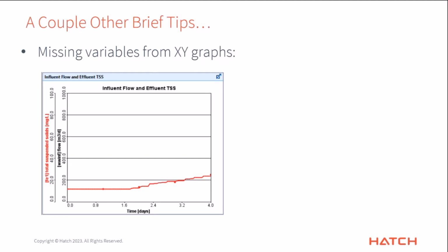And another one, just because the other day my colleague Jake and I were helping out a client with this exact issue. We were plotting this graph, but nothing's happening. Where we see the red line, where's the black line? It's not showing. And the reason is that in this case, it was just an issue of what scale you were showing on your graph on the left-hand side there. And a really quick and easy way to see if something is not showing because it's off the top of the graph is to just left click on the graph.